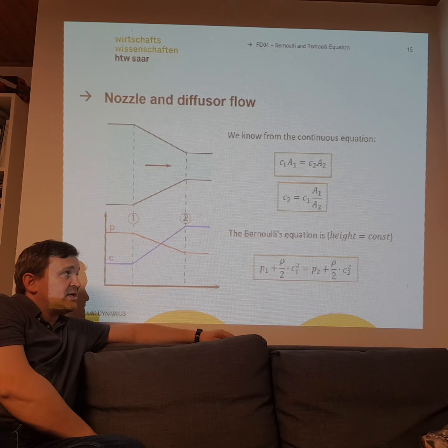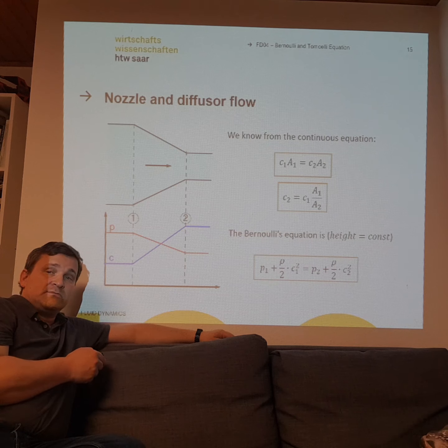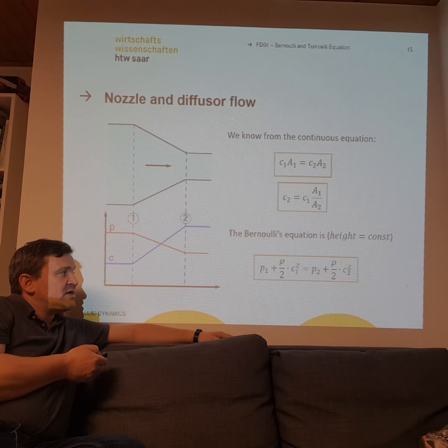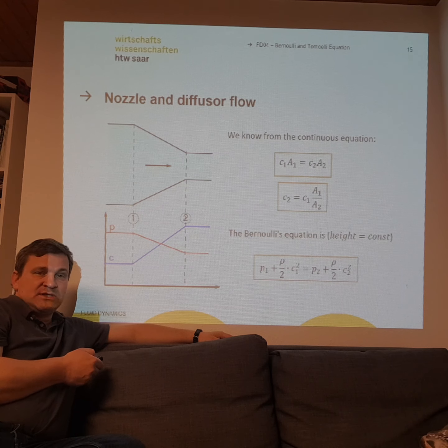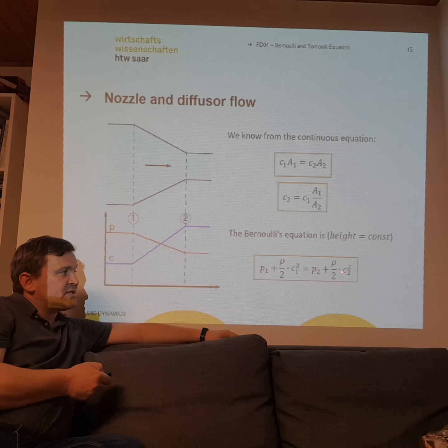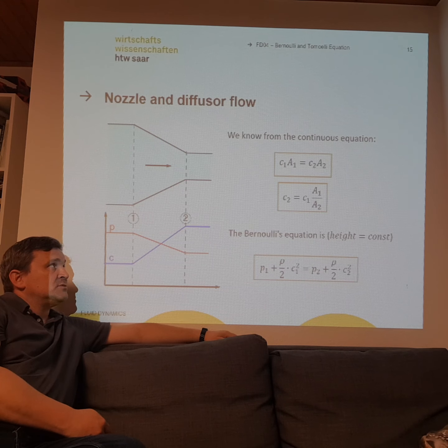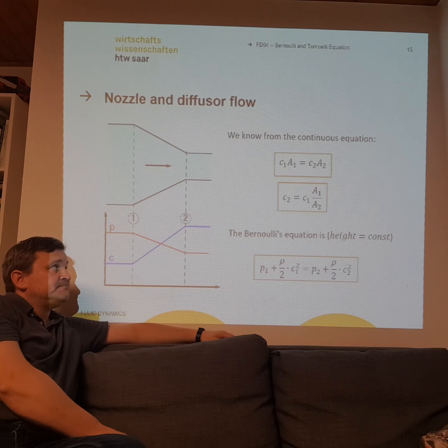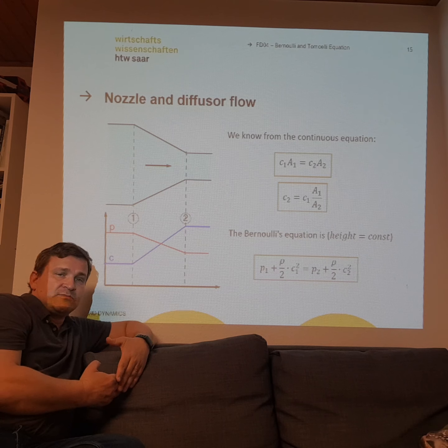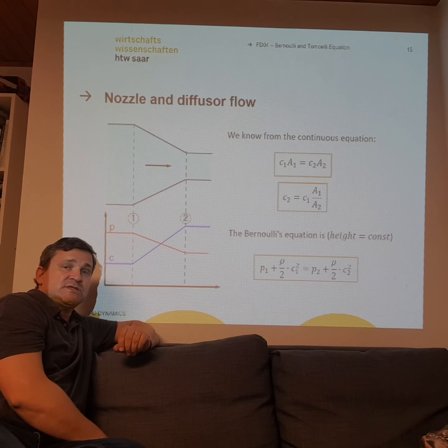This can also be explained by Bernoulli's law. If it is a balance and on both sides there are the same energy amounts inside the fluid, and if we have a high pressure and a low velocity here, we will have on the other side low pressure, then we must get a high velocity. So those are important laws, keep them in mind. And I think if you try to imagine a pipe system, you can also formulate this area dependency on velocity on your own.